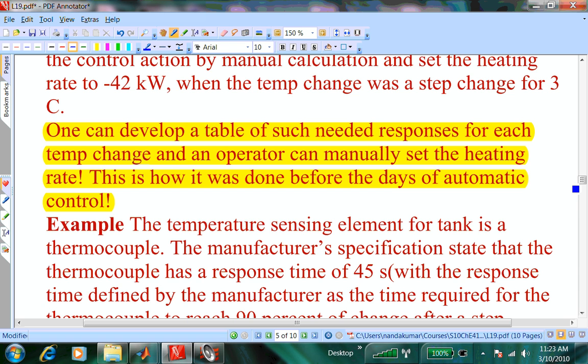There are problems later on. We are going to see about stability issues. We already talked about an idea of what stability is, but control systems, when you're tuning, you can tune them in such a way that the control action that you take is overly compensating for what is happening. If you get into that loop, the feedback control system will be unstable. Feed-forward control system becomes even more unstable, particularly if your process knowledge is not true. Because you're anticipating some change and making an action, but it's the wrong action, the process goes uncontrollable, unstable.